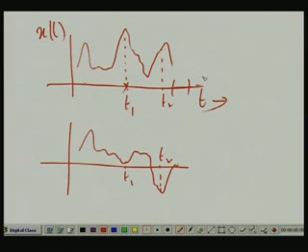This process is as much random at origin as it is at t1, as it is at t2. This randomness property, as given by the statistics, that is the probability densities, is the same whether you are seeing it at origin or at point t1 or t2 or any other point. Then it is called a strict sense stationary process or SSS.